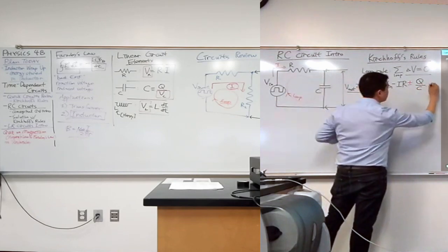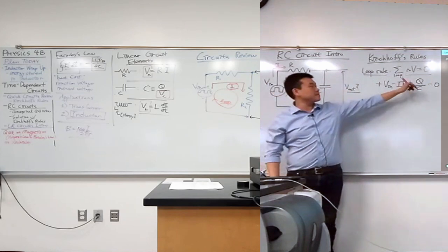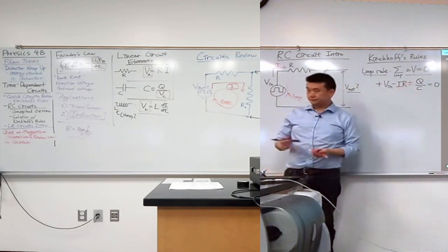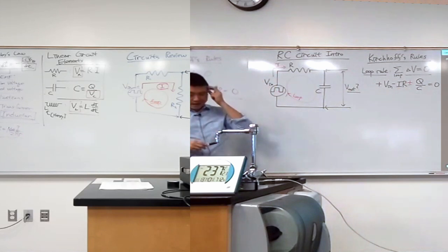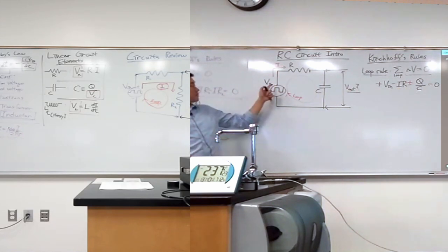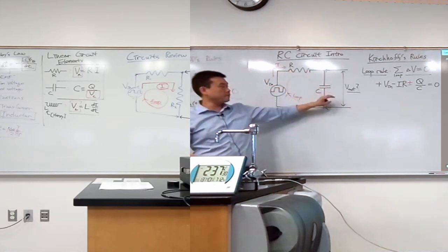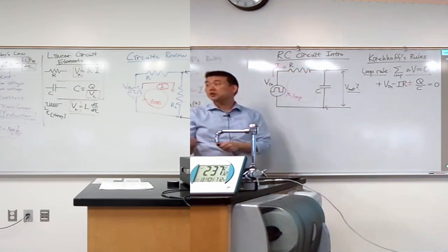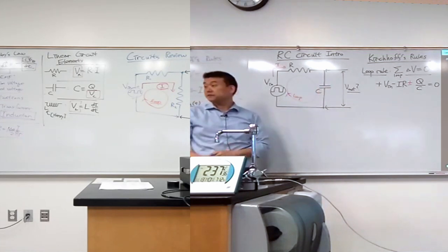So that brings me back to the loop. That should equal 0. I should spend some time picking whether this is going to be plus or minus, to avoid a sign error. This is the exercise I like to go through. Imagine I have these positive charges flowing this way. As they start to accumulate, if my capacitor wasn't charged, which of the two plates ends up being positive?